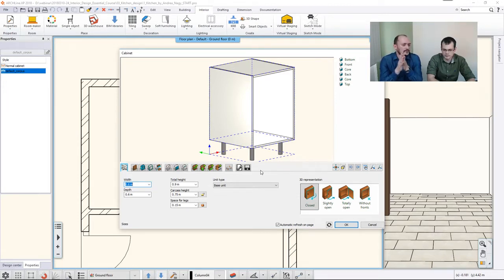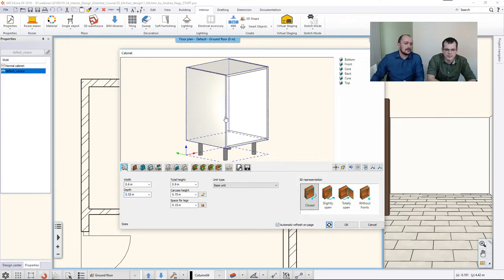Let's go through the basic settings. First things first, of course, you need to set up the width, the depth, and the total height of this furniture. These dashed lines are helpers to understand what changes and how that measurement, that value, that width and depth changes the item. If you change the depth, for example, and see I'm doing that, changing it to 0.55. I'm working in meters, but you can change it to anything else. So if I change that and I click on update, the software updates the size, and now it's a little bit more shallow, and it's always from this point to this point.